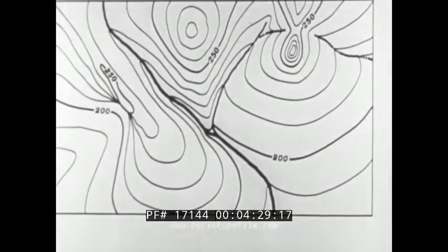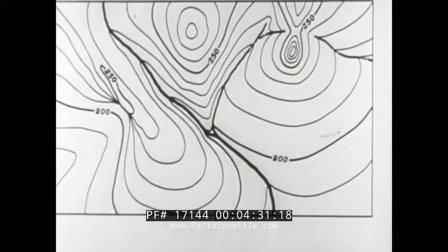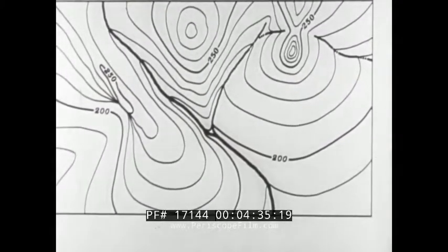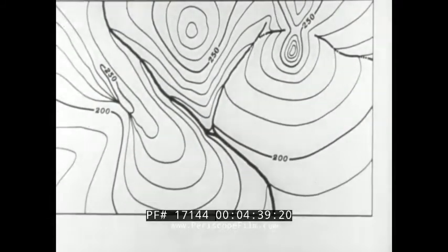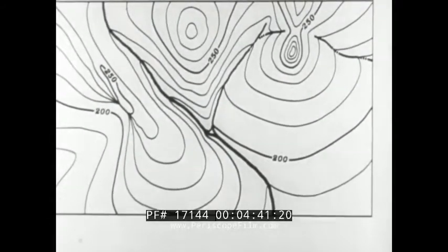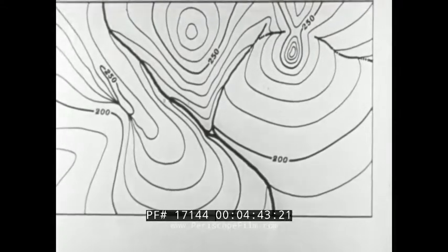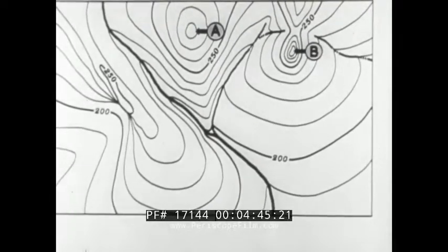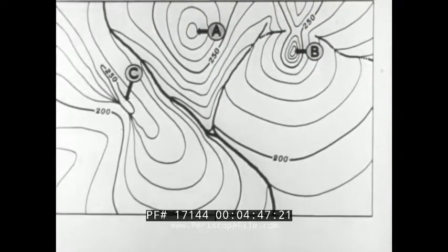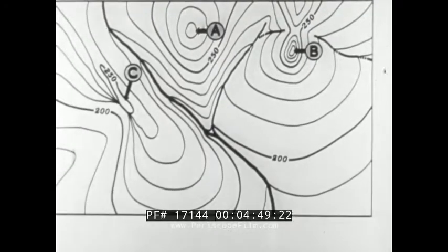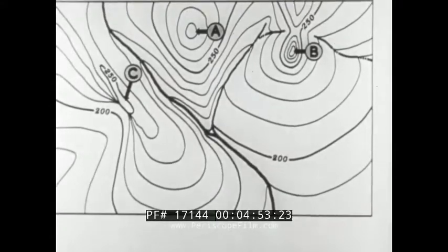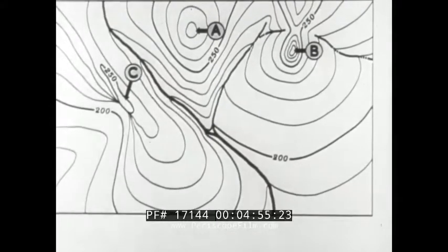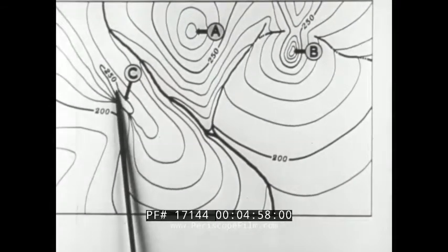Where they are evenly spaced, a uniform slope is indicated. Here is a section of a contoured map showing typical ground form. The characteristic wavy form of the contours indicating irregularities of the ground is at once apparent. The numbers signify the vertical heights in feet above mean sea level. At A, B, and C, the contours are closed curves. Since these contours are higher than those outside of them, they represent hilltops. At A and B, the tops of rounded hills. At C, the crest of a ridge.